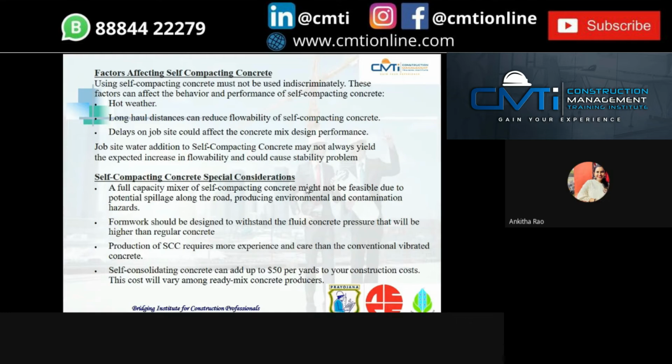Self-consolidating concrete can add up to $50 per yard to your construction cost. This cost will vary with the amount of ready-mix concrete produced. Money also matters, so suddenly we can't change normal concrete to self-compacting concrete. So everything should be pre-planned.